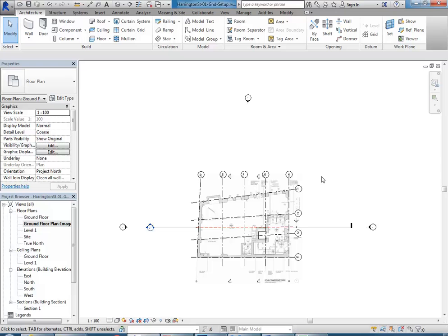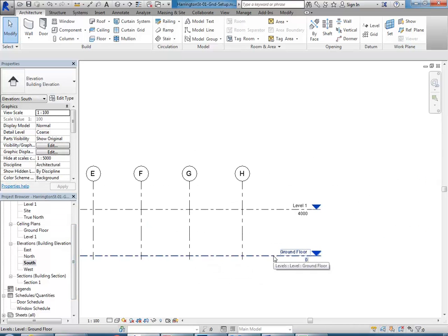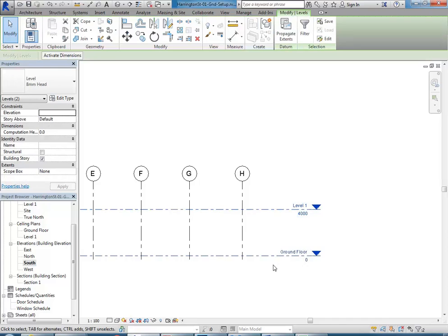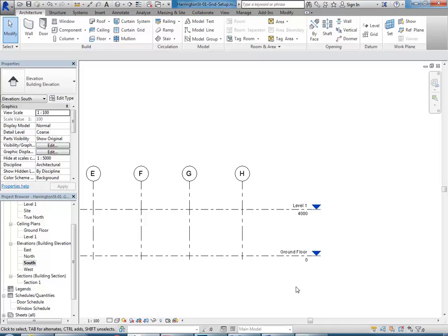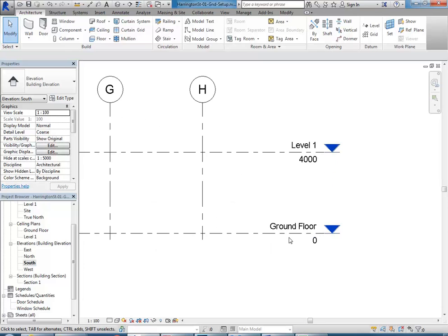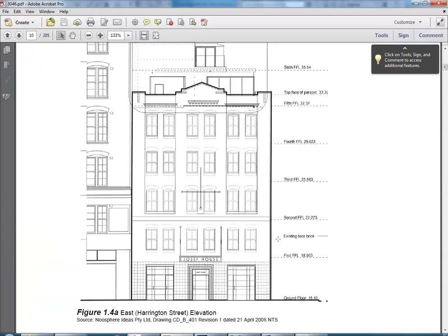And so you'll see if I go now and open up an elevation view, south, we're at 0 at the moment. So I'm going to have to move this up 15 metres to get that number there to appear as 15,100, which is really what we want. So I'm going to do that, but again, make a decision when you have levels that are greater than that, and you can always reduce it or use reduced levels and say, 30,000 is my 0 point, and work from there.